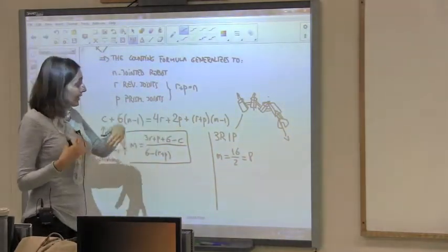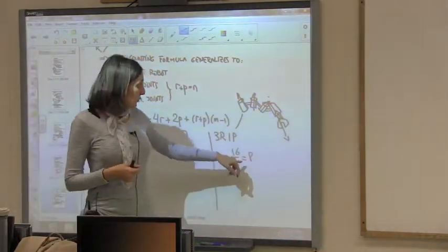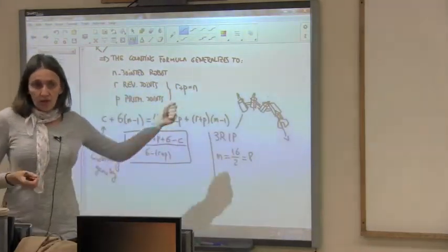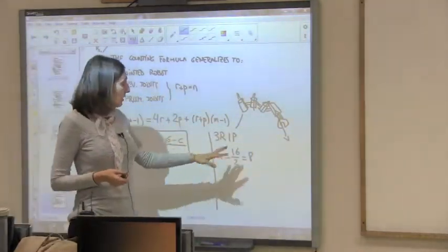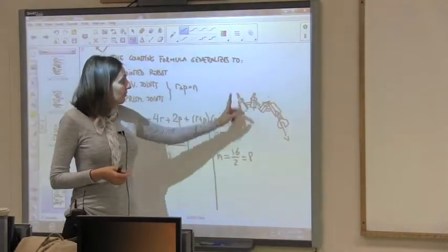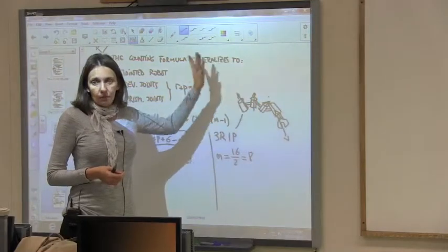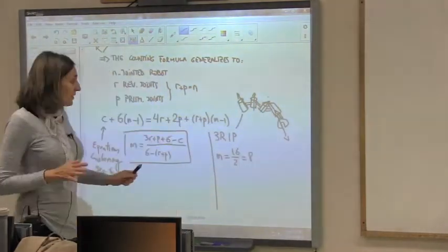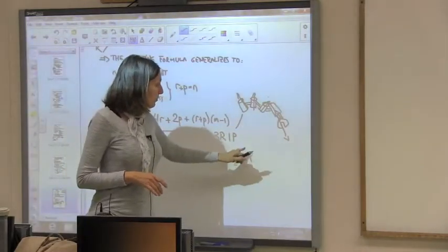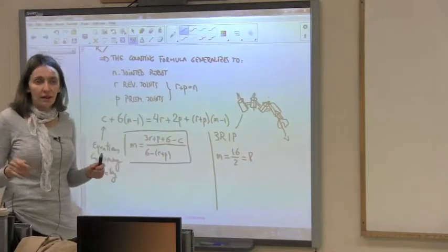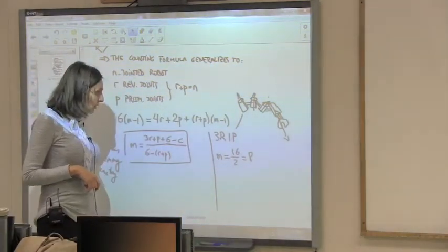What happens if you define less than this? For instance, less than 8 positions for this robot? That means you have infinite solutions. You can select something arbitrarily. For instance, I define 4 positions or 5 positions, and I'll fix the first axis to be vertical and be located here, for instance, right? When we solve for the exact number of positions, we don't have any freedom as designers to specify anything. Everything is given by the calculation.